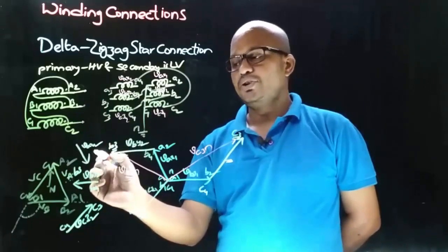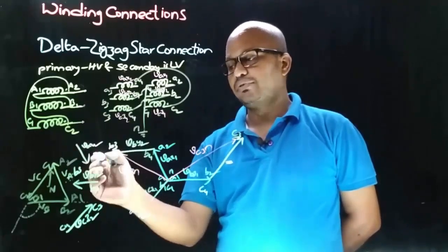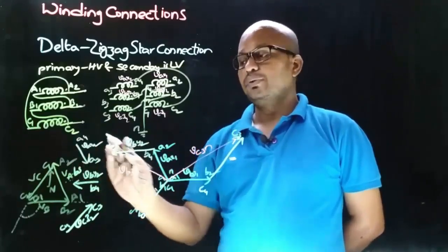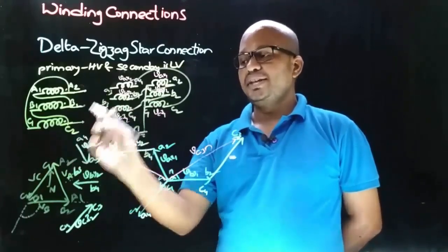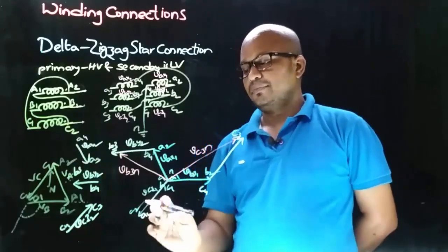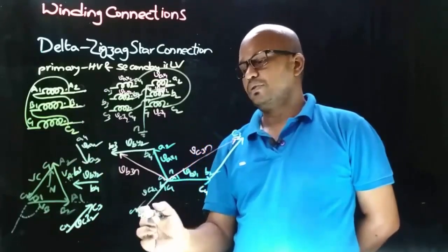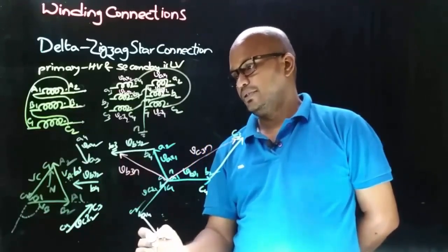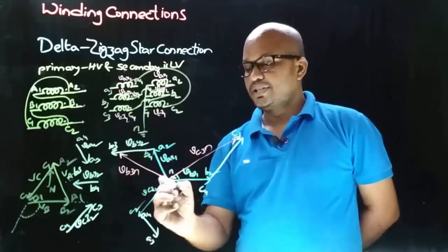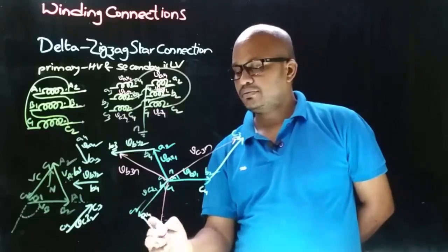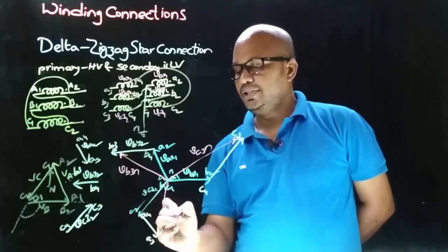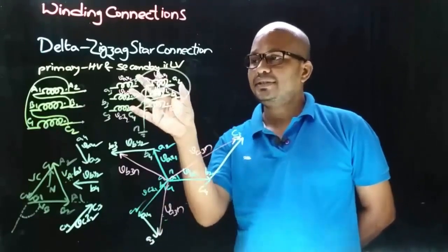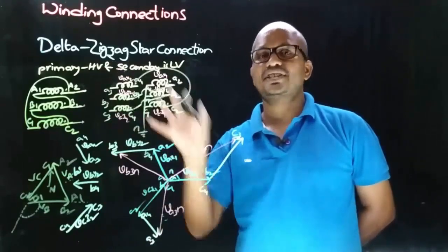Therefore the arrow points towards the connection we took from, that is A3, and the other end will be A4. Therefore draw this VA-X2 phasor such that C2 will have A4, like this. This is A3. Therefore the resultant voltage is VA3N. This is the phasor diagram for this type of delta zigzag star connection.